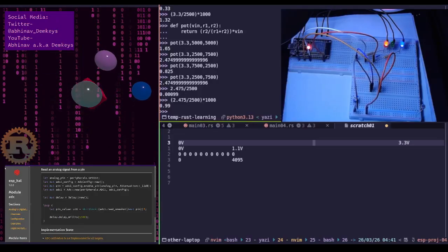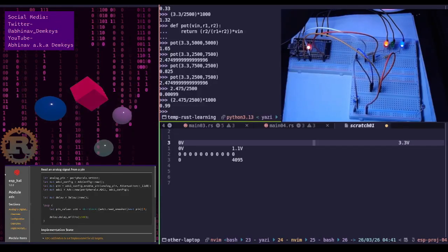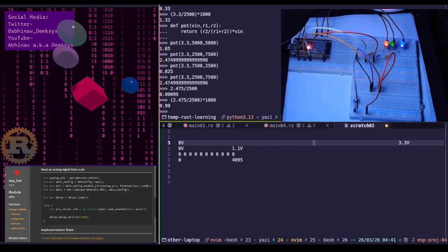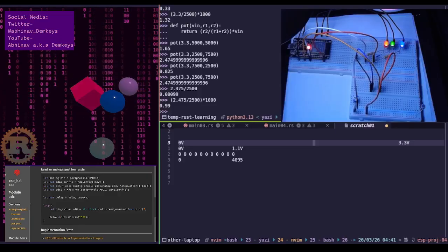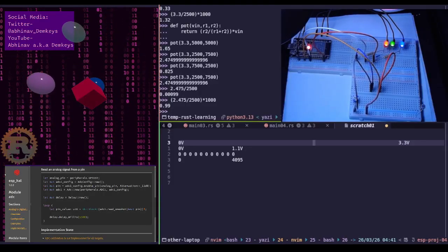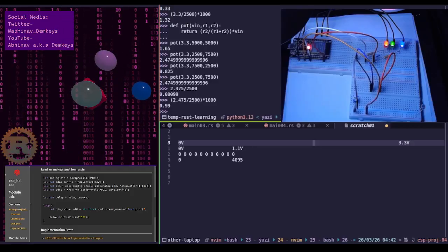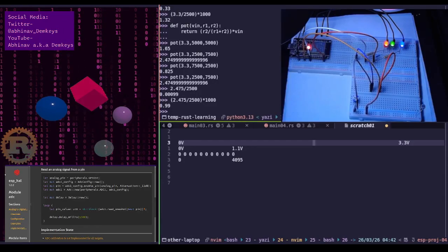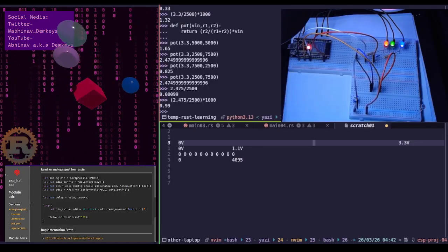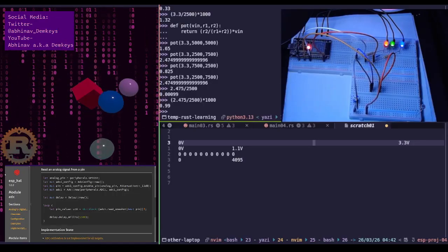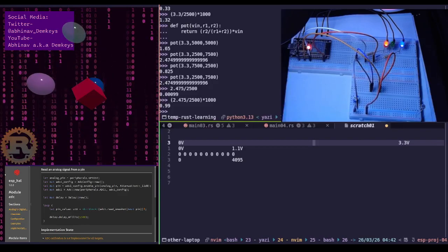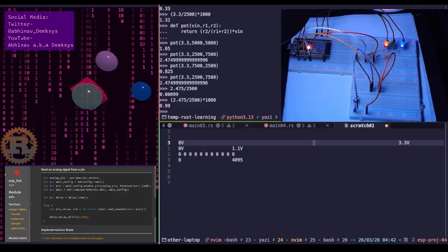All right. Then current, the high impedance shield. You might worry that turning the knob to the 3.3 volt side will shove too much current. I actually was worried about that. And then I did the I equals V divided by R calculation. Basically, I did the current calculation, and it's 1 milliamp. Okay, yeah, let's continue reading this.